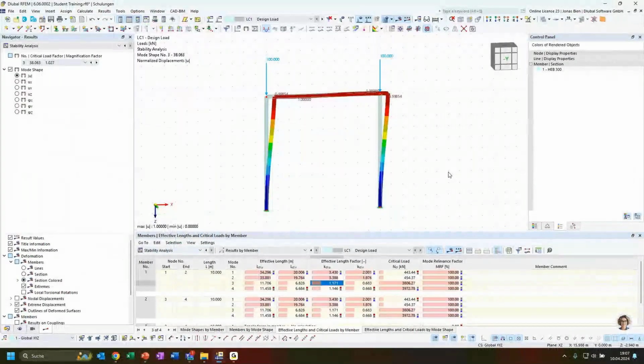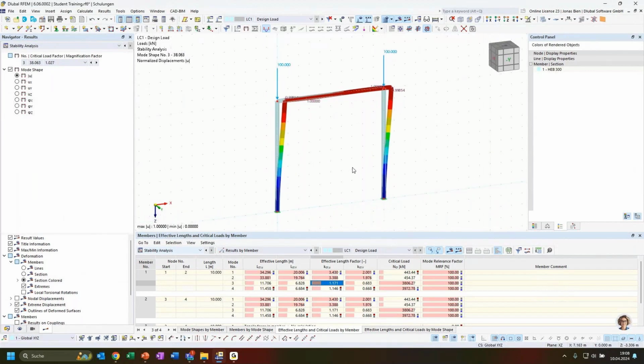But anyway, it's always wise to start with a problem that you know how to solve. So start with simple problems that you know the analytical solution for, and then increase the complexity step by step. That's generally a good approach when learning a new tool for your engineering work, such as RFEM in this case. I would definitely recommend you start with known problems and with low complexity, and then increase the level of complexity and see if the results are still reasonable and what you expect from it. It's always a good approach.